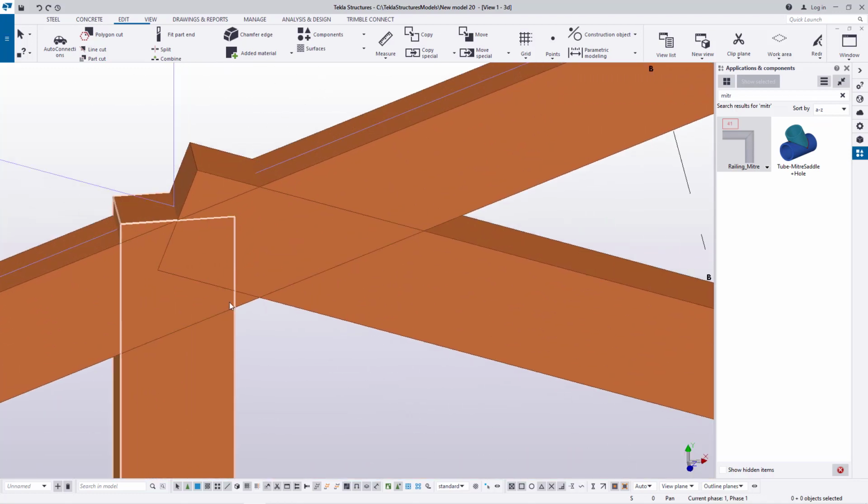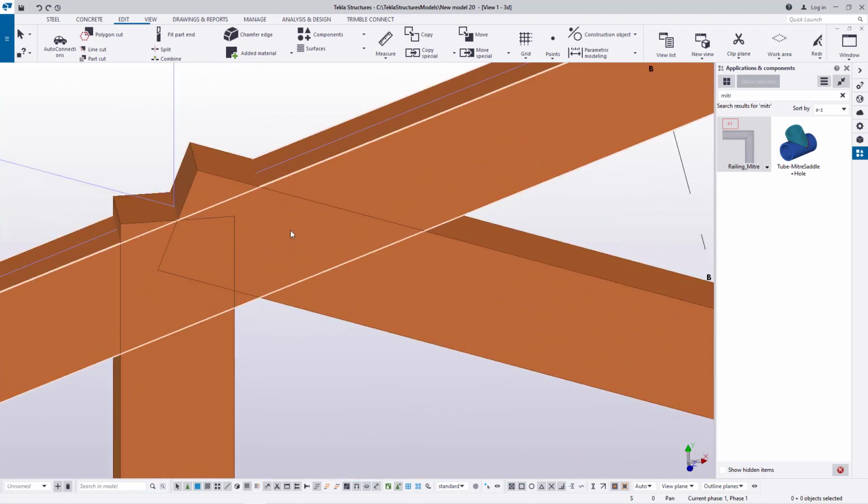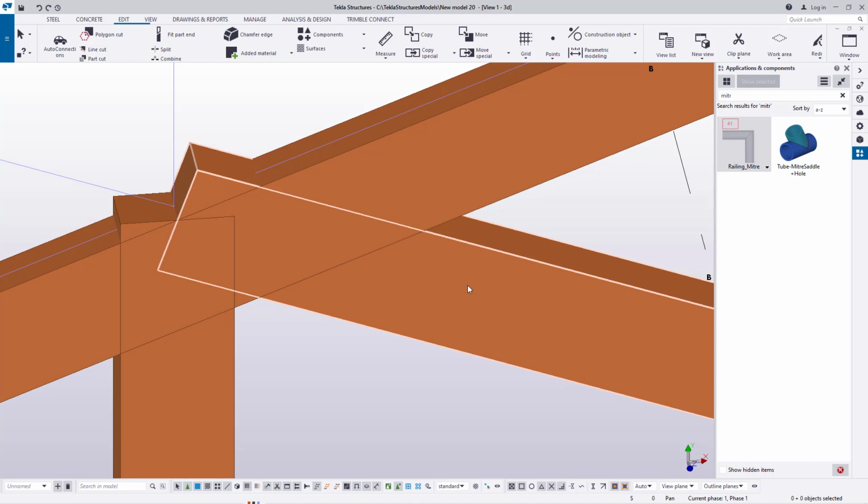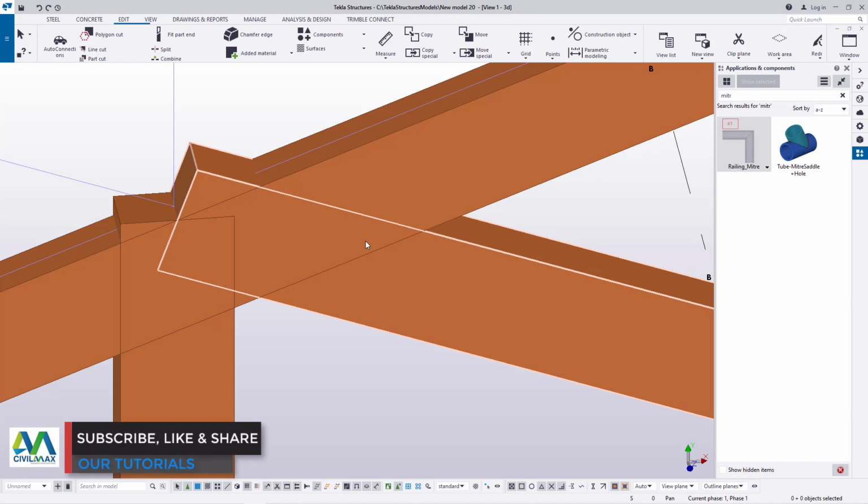in one go. So let me first of all show or define the connection between this top chord and this strut. Now I'll connect them by a mitre, a tool that is normally applicable on steel connections, but we can apply it here, knowing that this is a steel connection. So when you generate your drawings, you know how you detail and define this connection. But in this particular case, in the next presentation, I'll show you how we can apply bracket connection for these timber members.